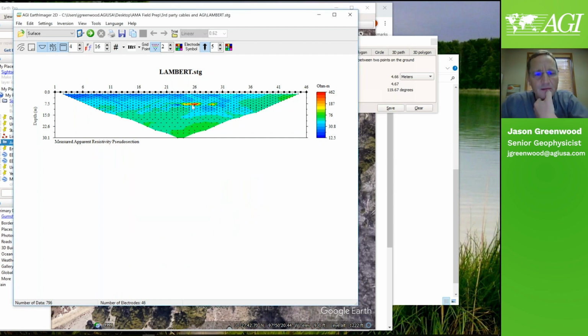And from talking to the end user, they told me in this case the low address portion was a third-party cable. It was colored red. It's a non-AGI type cable with a different manufacturing method, so a third-party type of cable, and those are known to have some issues like this. So you can see those in the raw data.